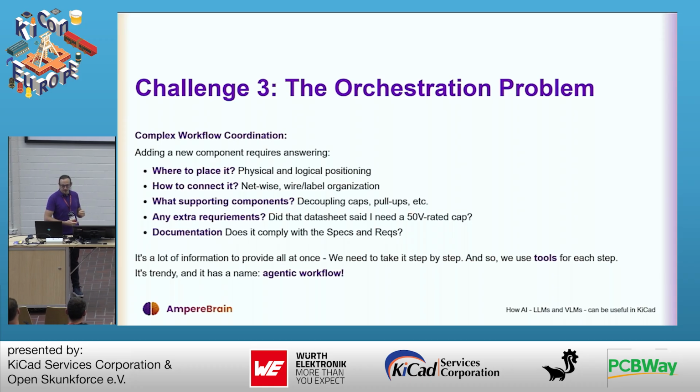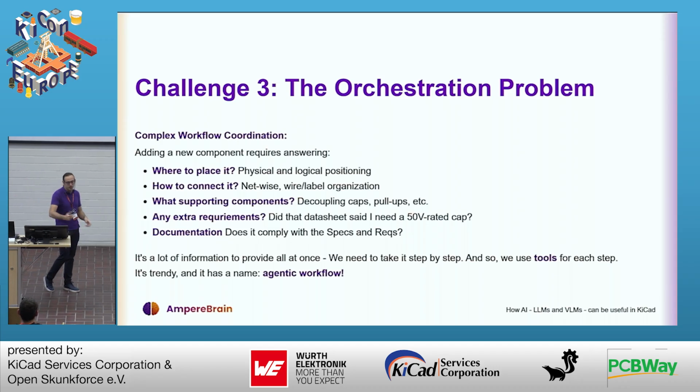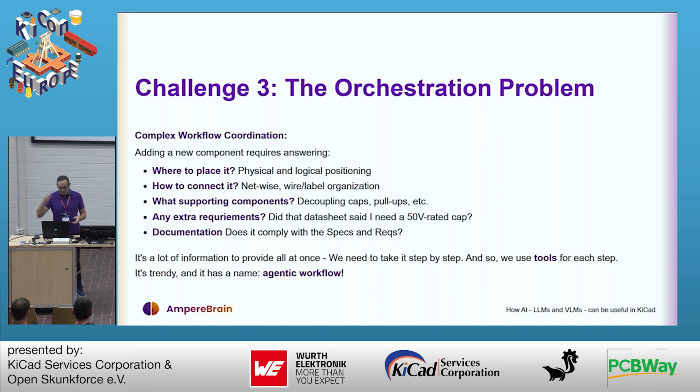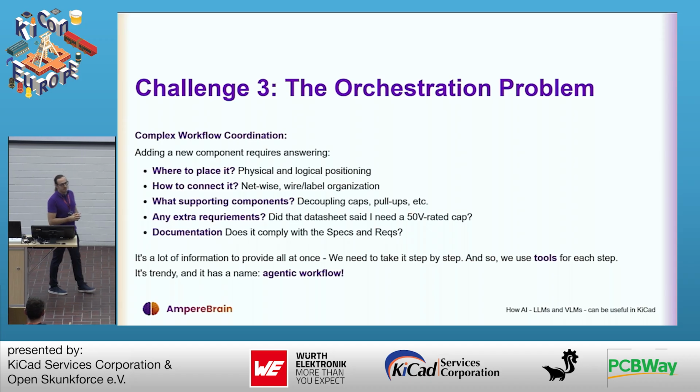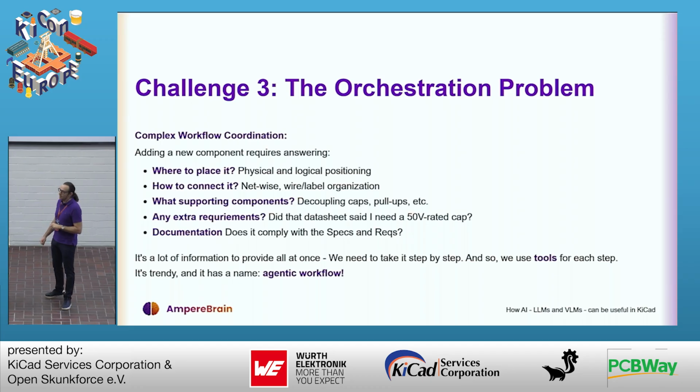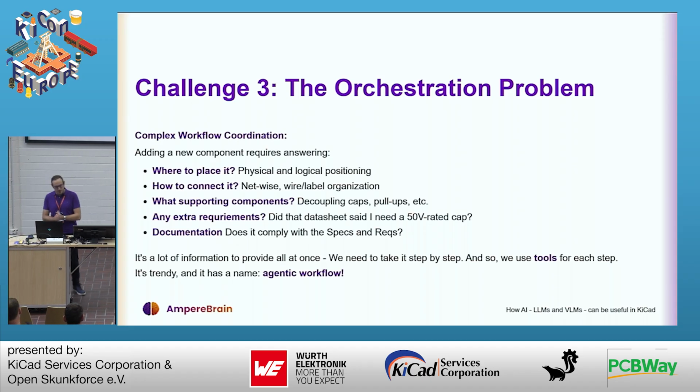Then, of course, how to connect it. And how to connect it, there are 2 levels. It's, of course, netwise. But it's also, okay, do I connect it to my other components with wires, with labels? So that's the next question. Also, do you need any supporting components like a decoupling capacitor? Also, do you have any extra requirements where any engineer would basically make a note saying, hey, I need that crazy capacitor for my design. Please don't forget it when you do the BOM. That's a good way to screw up a design.